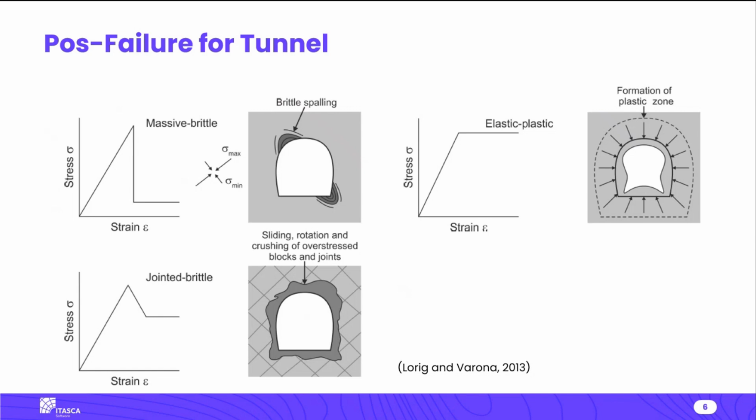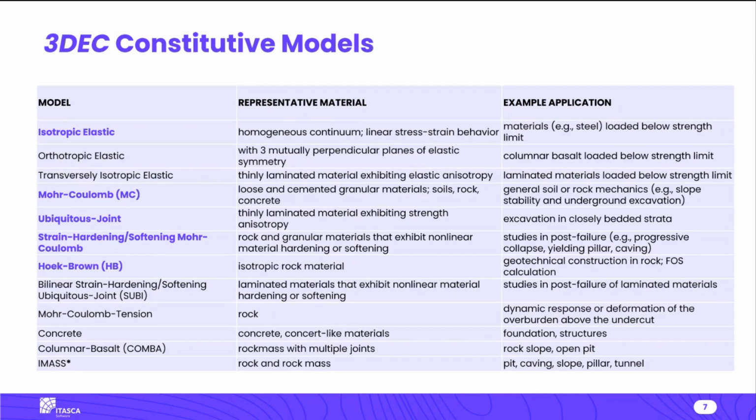There are many, many constitutive models inside of 3DEC. This is not all of them. These are the ones that you will probably likely use. I'm assuming for this presentation that you're probably modeling rock. If you're a soil mechanics person, likely you are doing FLAC 3D or some other continuum program. 3DEC, as you probably know, is mostly used for modeling rock because of its ability to consider joints and discontinuities and things like that that are common in rock.